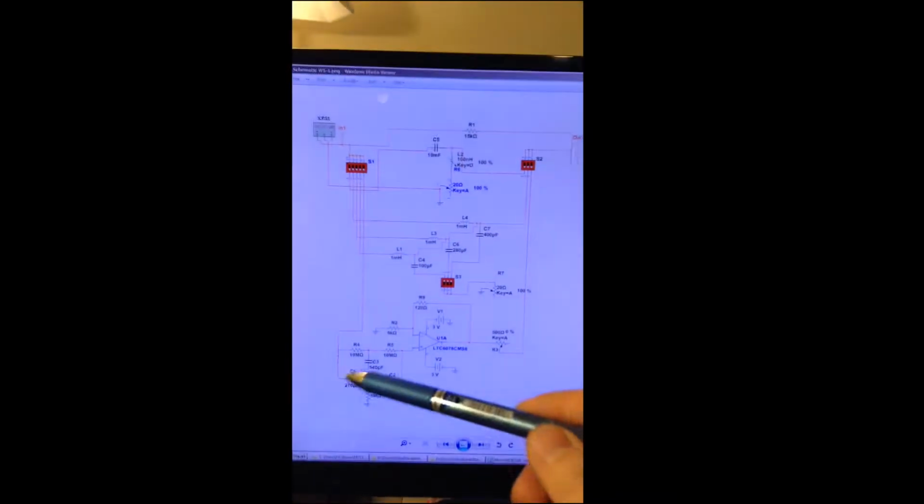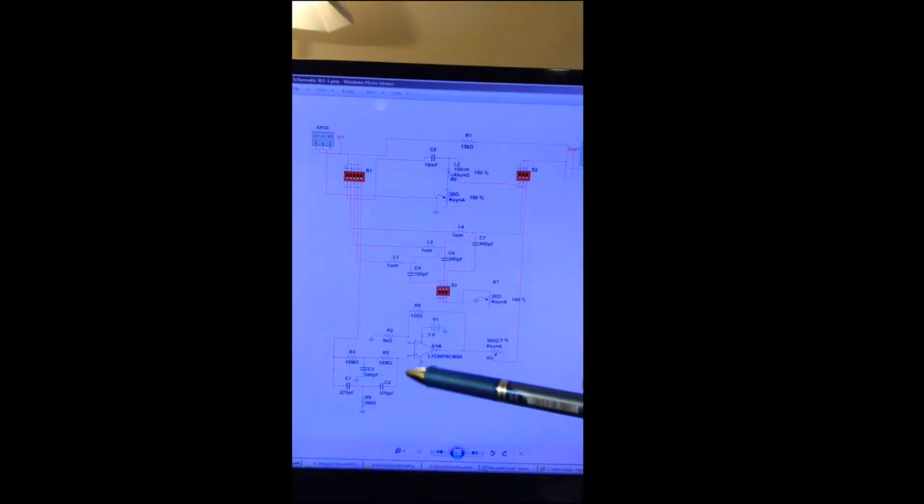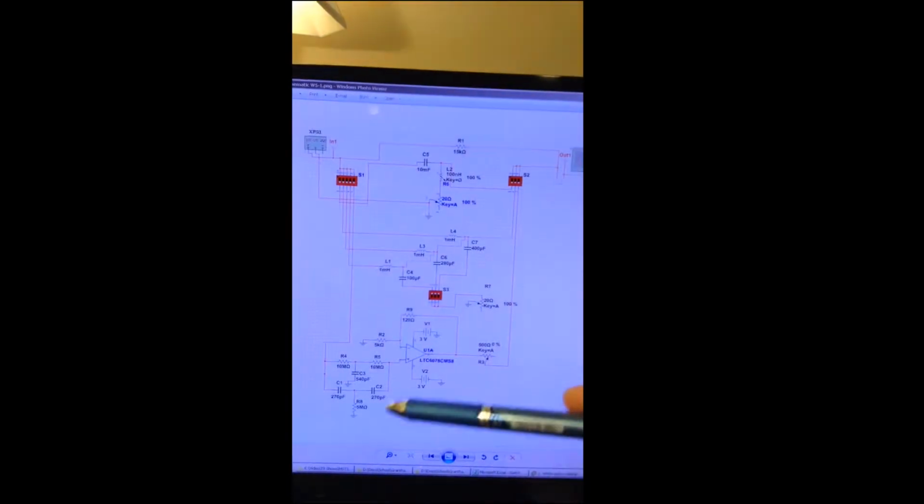This last section here is the split T filter or twin T filter, which provides 60 Hertz notch filtration. We have an op amp here which provides amplification because this filtration system will bring down our usable signal as well, and we need this amplification to bring it back up to where we wanted it. So the op amp brings everything else that we want back up to the normal level it was originally, except for the 60 Hertz peak, well, negative peak that this filters out.